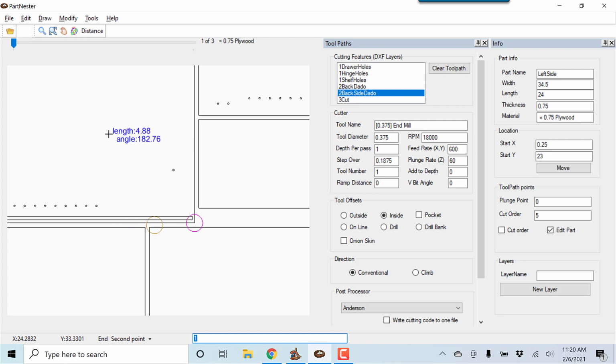And if you are familiar with other CAD functions, in the lower corner, I want to move, starting with an @ symbol, I want it to move, say, 3 inches. So again, I'm going to move 3 inches in the 180-degree direction. So 180 is to the left, 90 degrees is straight up, and then hit enter.